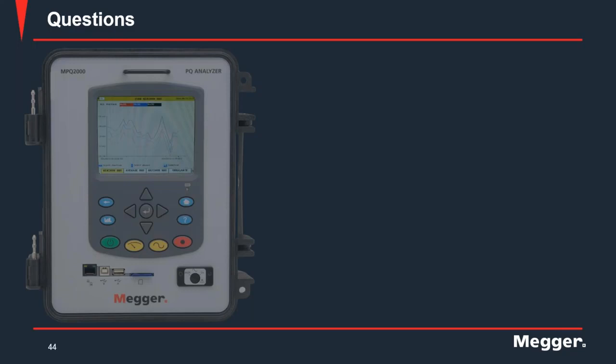Otherwise, you very well may be having problems due to things like harmonics, which are continuous issues. But in short, yeah, a power quality study can really tell you a tremendous amount about what's causing a problem and how to get the solution to it. Especially since we were talking about that first issue with the DC overvoltage bus. These are fairly common, especially when you get into your VFDs. Of course, you can have these problems from many things, like just the backfeed from a motor can cause your overvoltage bus. So there's quite a few different things, and the PQ study can do that.